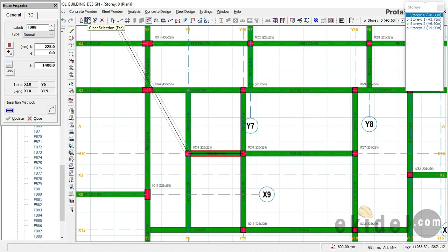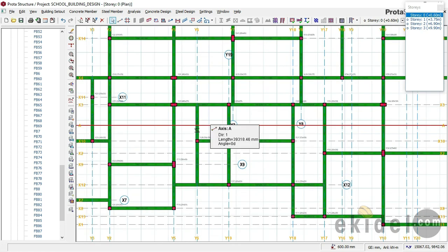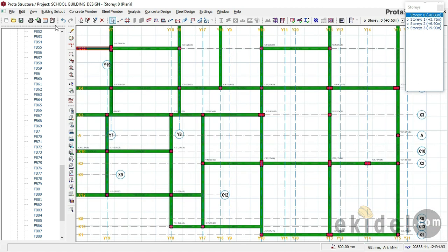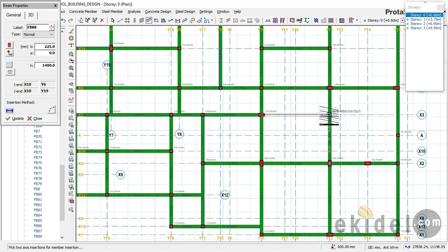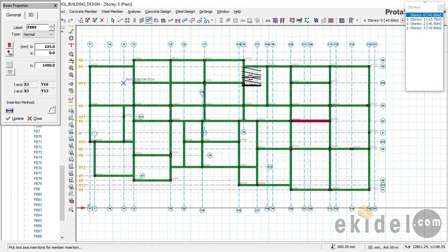But if you check our upper floor, there was a staircase here, so we left it as void. But here on the raft foundation, we don't consider anywhere as a staircase, because everywhere must be slabbed. Okay, that's fine. So let me do it again. I can connect this one to make it stronger. Also, I can put my beam here and then connect. The whole idea is to connect all your columns with ground beams. So that's why I'm doing just that. Okay, so again, that's fine.